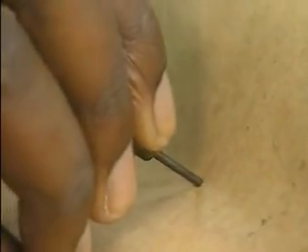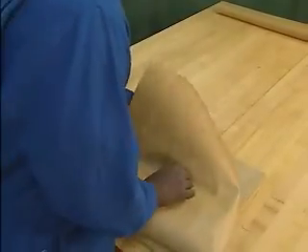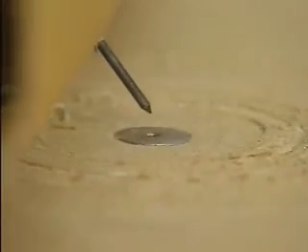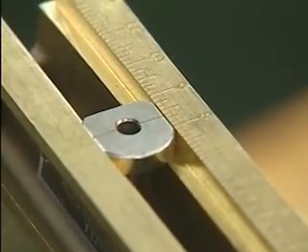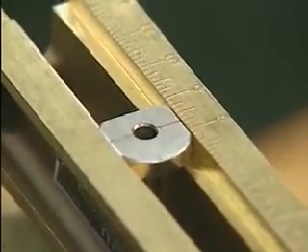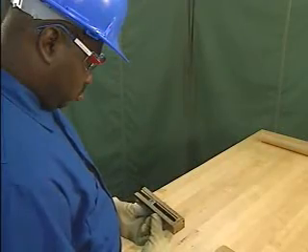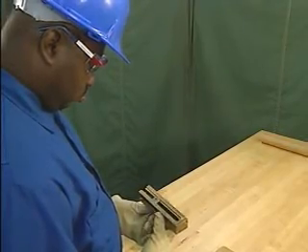Next, the mechanic sets up the gasket cutter. He pushes the pin through the gasket material, then places the pin in the hole on the cutting board. The mechanic then positions the cutting blade using the outside diameter measurement so that it will cut the outside edge of the gasket. The outside edge should always be cut first.